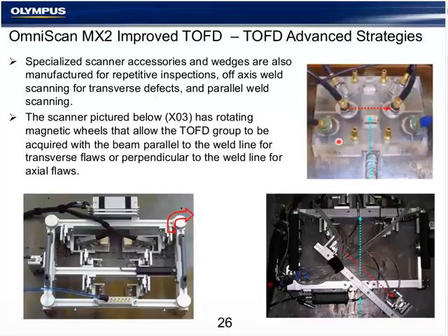This would be maybe good for a high production, high volume facility that uses a finite number of weld bevels, such as a windmill tower or some other type of construction. There are positives and negatives with this type of setup. The benefit is it's extremely easy to set up and get running, but your ability to manipulate the probes and to couple well and provide total couplant across all of those requires much more water and a smooth pipe surface or tower surface.